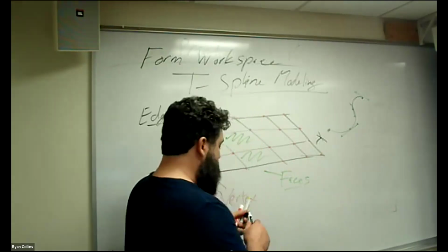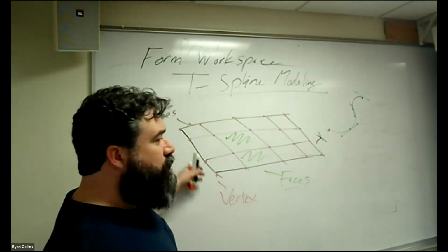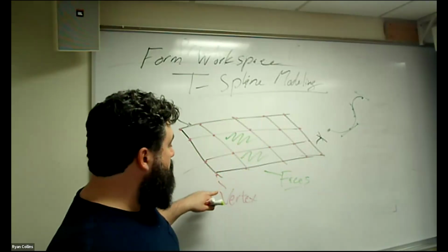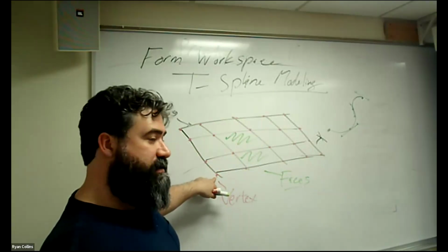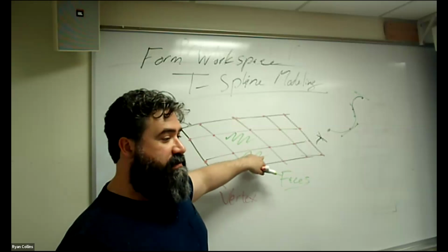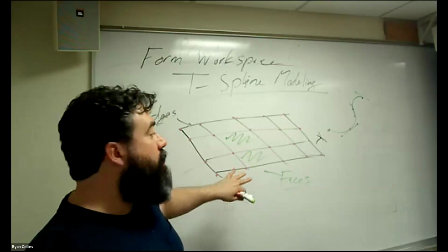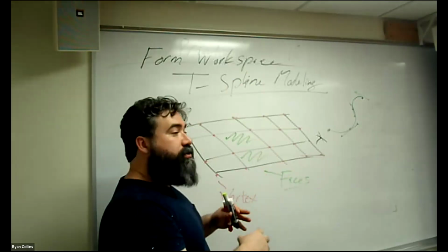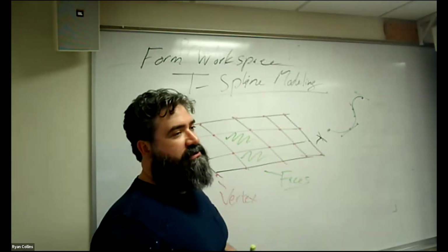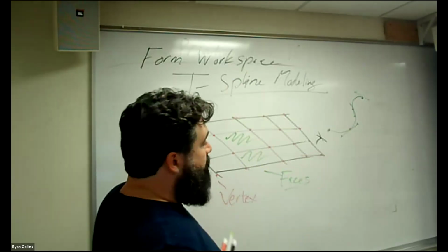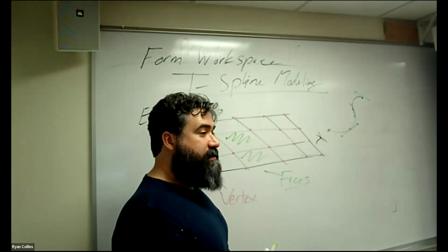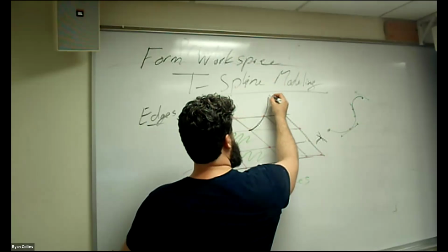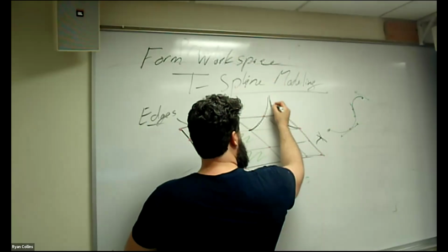That's a T-spline model. How this functions, though, is you can control by any number of these options. Meaning, you can grab and morph things by vertices, by edges, by faces, or by all of them in between. You can grab them, push them up and down, stretch them back and forth, scale them larger and smaller, you can even extrude them, depending on the things. But the reason I said think of this as a big net, what happens when you pull on something? You can pull upwards, and all of that follows with.